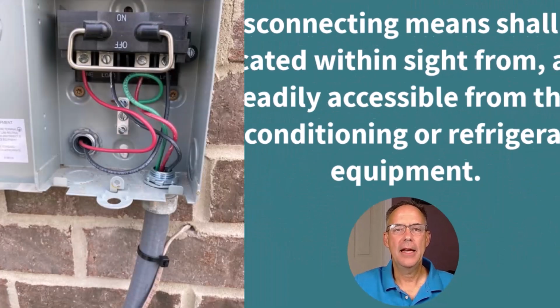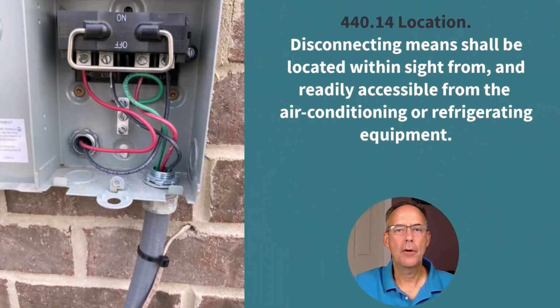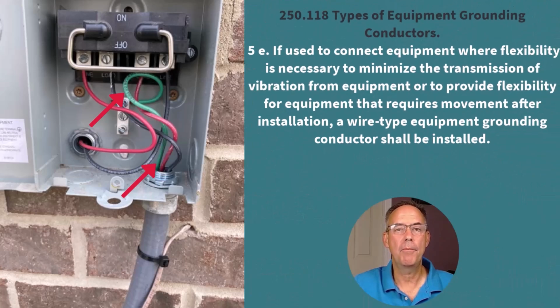Now, from the disconnect to the unit, the code allows some type of a flexible conduit, like a liquid type flexible conduit. But an EGC, equipment grounding conductor, always has to be provided, because according to 250.118, they want an EGC of the wire type provided for any equipment that has vibration issues, so that there's a solid fault path back from the unit to the disconnect back to the source.